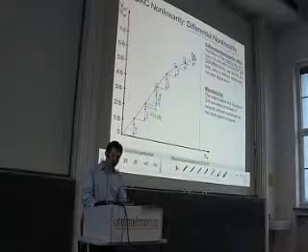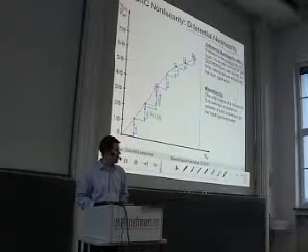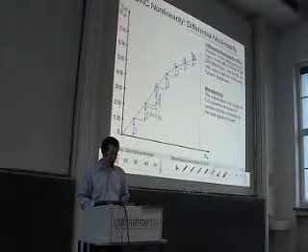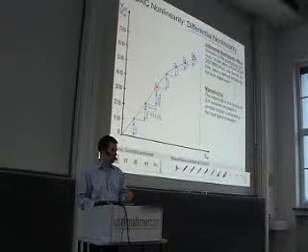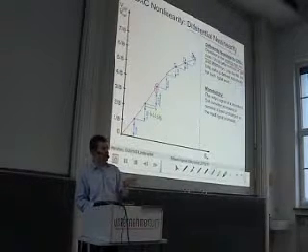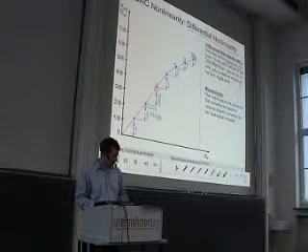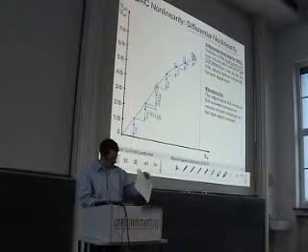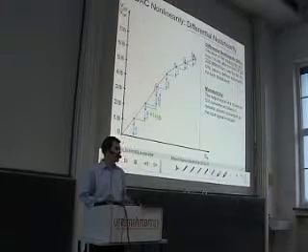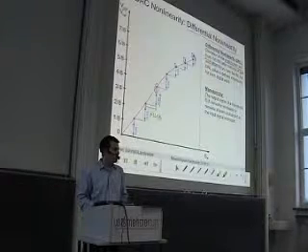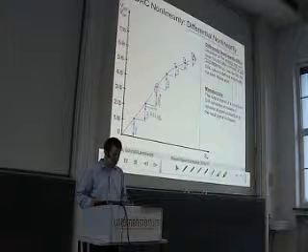One important property of a DAC characteristics is also the monotonicity. The monotonicity describes that if I increase the input word, then the voltage goes up. If I decrease the input word, the voltage goes down. This is an important property that is called monotonicity, in particular important if you have control applications where you use a DAC or later also an ADC in a control loop.